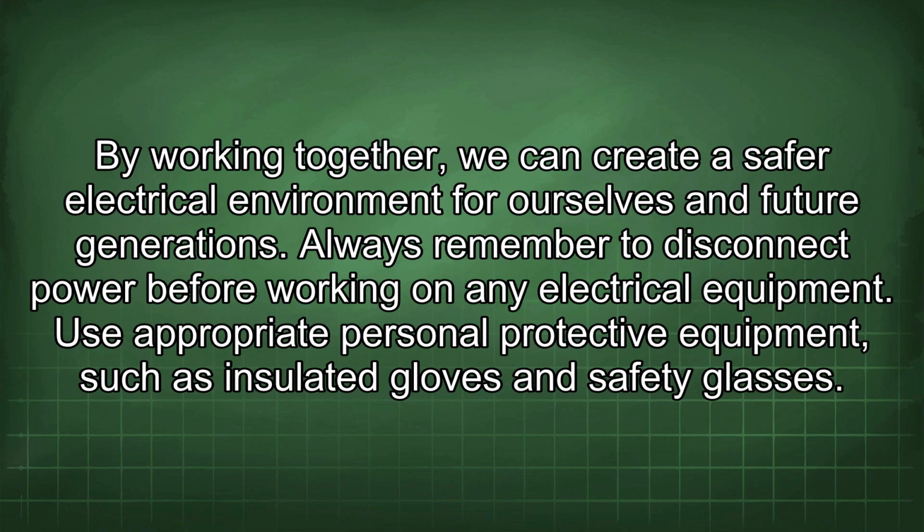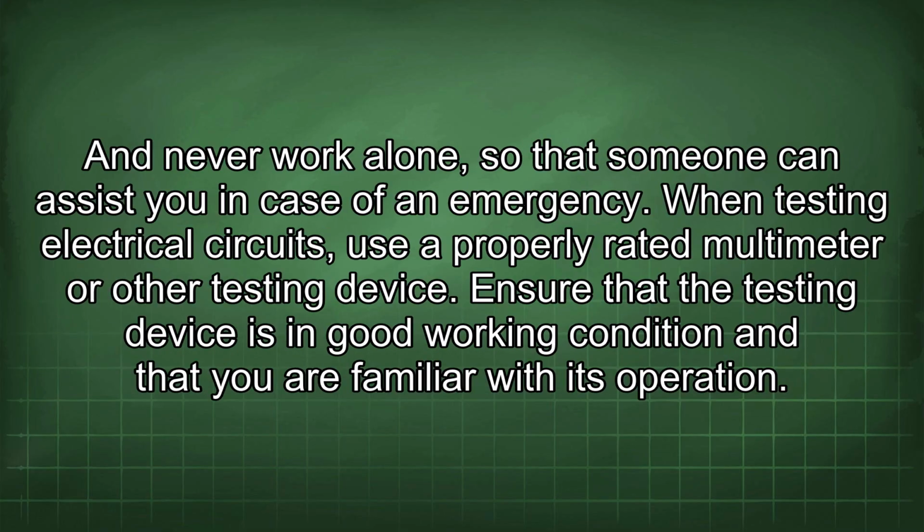Always remember to disconnect power before working on any electrical equipment. Use appropriate personal protective equipment, such as insulated gloves and safety glasses. And never work alone, so that someone can assist you in case of an emergency. When testing electrical circuits, use a properly rated multimeter or other testing device. Ensure that the testing device is in good working condition and that you are familiar with its operation, and always